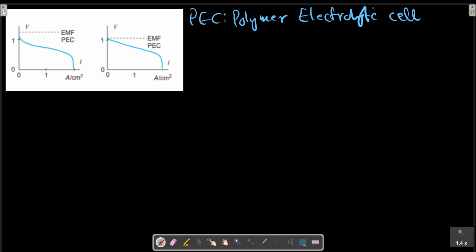Just the opposite is the case for the high temperature SOC solid oxide cell. As the current density increases towards the limit, the voltage drops sharply in both cases, as shown in these two pictures, and if the power per unit area, VI, were shown, it would have a maximum in the middle range of current density.